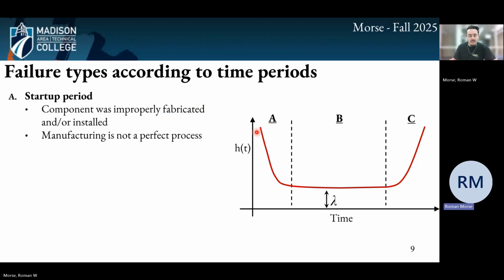So why do we have this high rate of failure at the very beginning, and then it kind of settles into a normal operation? Well, this is due to the fact that the manufacturing process for any component is not perfect. So even the best companies, let's say NVIDIA, for every GPU they put out, so say they make 10,000 of the same model, there will be five, six, seven of those that actually are faulty from the assembly line. Something went wrong in their manufacturing process, and it actually produced a product that was not viable.